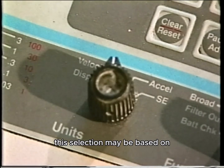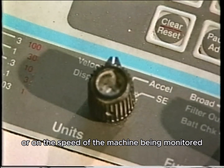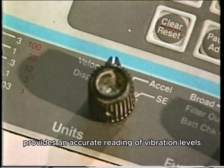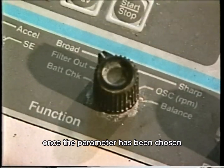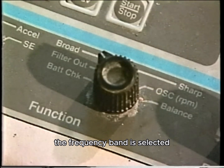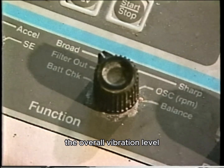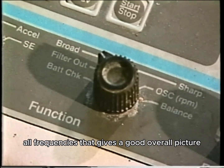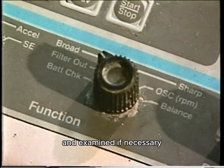This selection may be based on your company's vibration monitoring program or on the speed of the machine being monitored. Usually, velocity is checked first, since it provides an accurate reading of vibration levels over a wide band of frequencies. Once the parameter has been chosen, the frequency band is selected. Here again, it's a good idea to start by measuring the overall vibration level, which is the vibration that's occurring at all frequencies. That gives a good overall picture from which specific frequencies can be chosen and examined if necessary.